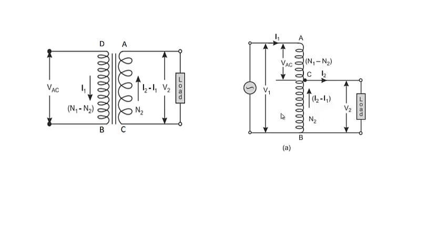A two-winding transformer is a transformer which has two separate windings or separate limbs, which are electrically isolated by some magnetic material, and they are coupled through this magnetic flux here. In the auto transformer they are connected directly electrically. There is a direct connection between A and C, and there is magnetic coupling as well.